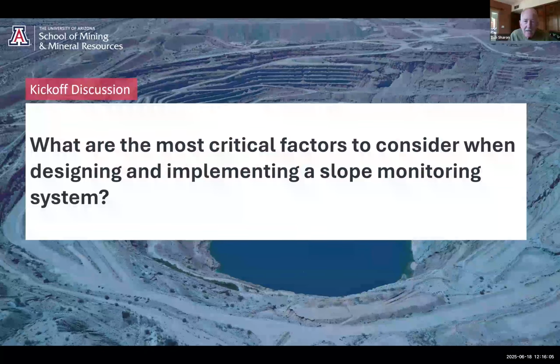One thing that I would like to add to all the comments that have been made so far is regarding developing a baseline of monitoring. This will help you to understand what the base conditions are. If, for example, you have prisms monitoring the slope, you're collecting data on total vector movement, rather than just line of sight that you might get with the radar systems and LiDAR. As Charlotte pointed out, we need to understand the capabilities and limitations of these instruments. So collecting that baseline information, for instance, if you have prisms on the slope, you're getting the total vector.